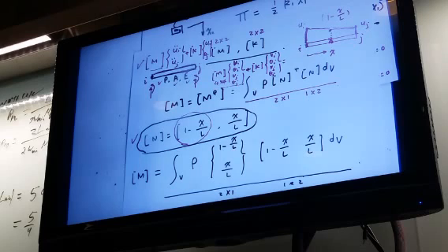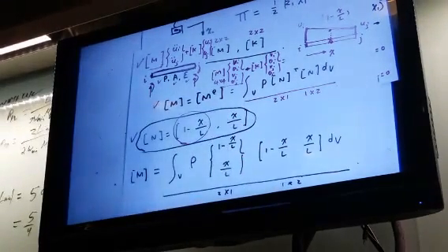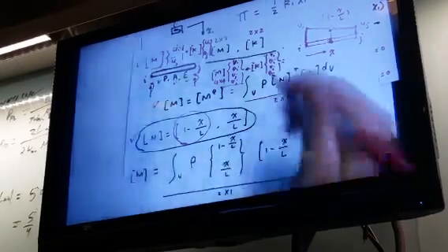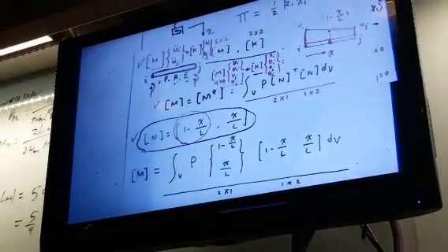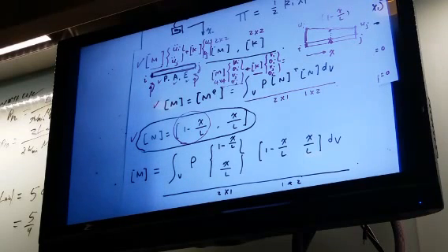And then you change the interpolation function. In ANSYS, you choose a so-called cubic polynomial interpolation. That tells you which N you are using for the beam element. I also give you some formulas for N. You will have N1, N2, N3, up to N4, so 4 different N. If you use those 4 different shape functions, you can construct the M matrix for the beam element. Okay? The stiffness matrix is the same as what you learned in the stiffness matrix method for the beam element. That is also a 4 by 4 matrix.